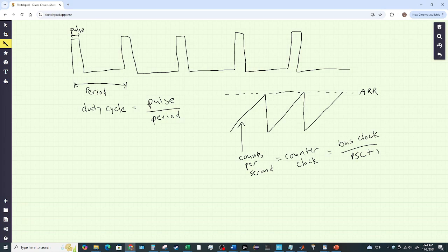A few things we need to figure out. Like I mentioned in the hardware demonstration, we have the stepper motor set to 1600 pulses per revolution, so 1 revolution per 360 degrees. Let's say we want to calculate degrees per pulse. Let's back up, or pulses per degree.